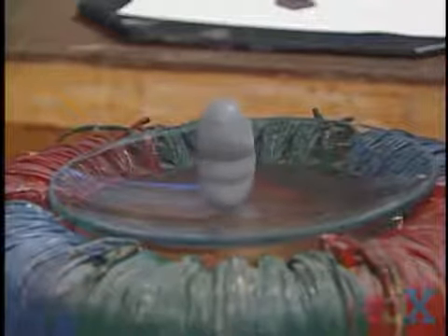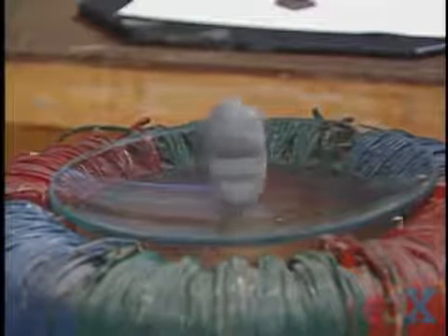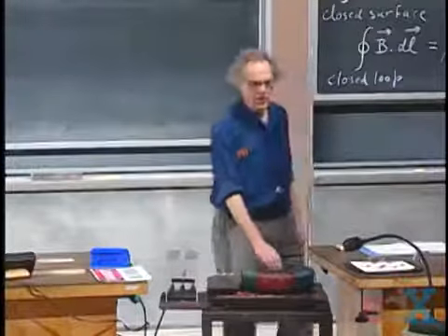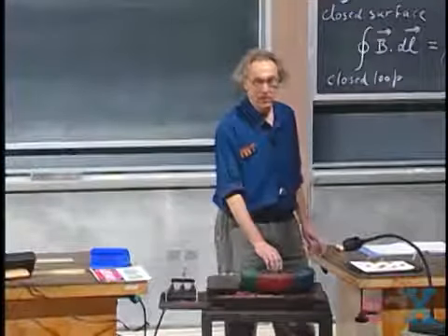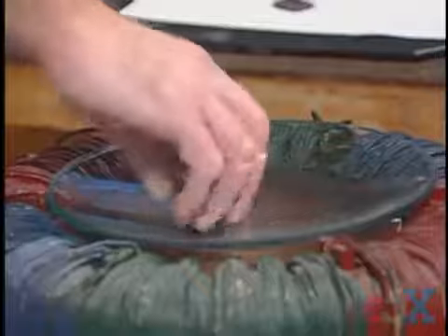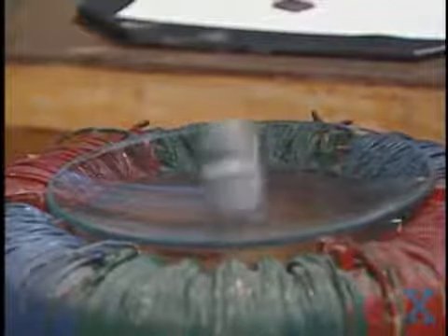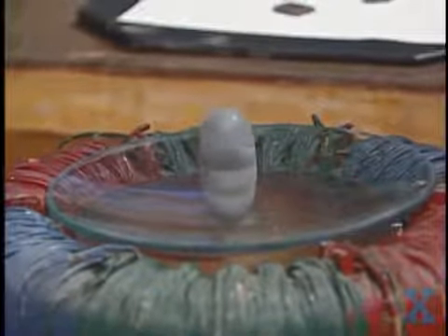It's only a little bit under 3,600 RPM. 3,600 RPM would be 60 Hertz. It's very close to that. If I spin this object in the direction in which the magnetic field is not rotating, then it says, sorry, no way. It just reverses, because the magnetic field is going to slave it in the direction that it wants it to go. So you're looking there at an induction motor.